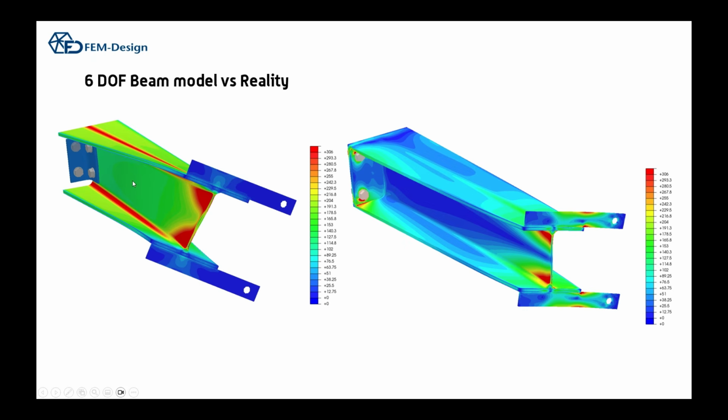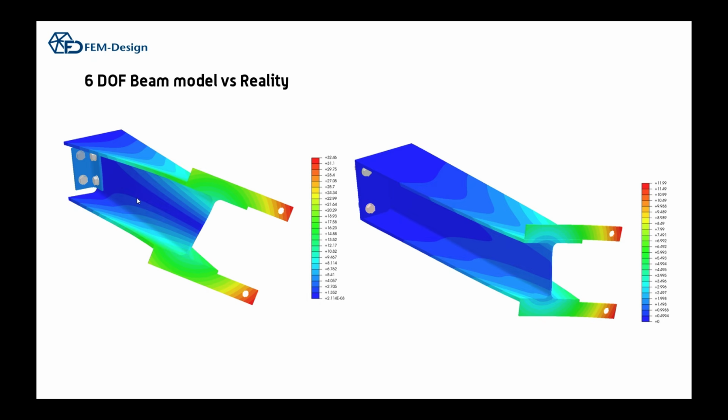So if you look this side, you can see the same torsion flows through the center of the beam, or mid of the beam, and the stress state, how they are carried in the beam, is totally different if you put the flange. So the exact same external forces cause totally different stresses if you prevent the flange movement.